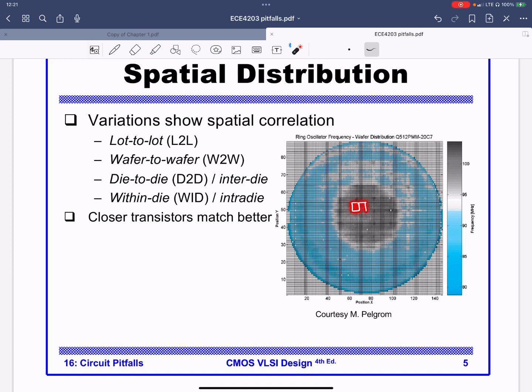Inside the chip, part of the circuits would be running slower and part would be running faster, depending on where it's printed on this wafer. So depending on the size, these variations could mean you have variations inside the chip. That means one flip-flop in one corner of the chip will have a different setup and hold time than another flip-flop in another corner of the chip.